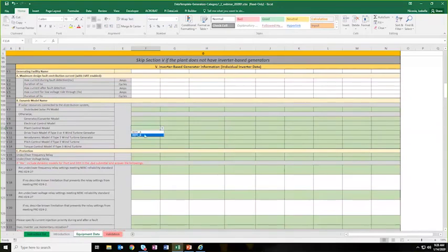Yeah, so here on the REPC model, I want to emphasize that REPC_B is preferred if you model multiple equivalent generators for the same plant and the voltage control is coordinated among those units. REPC_B has the capability to control multiple devices. It's better than the A because we have seen in simulation that when there are multiple generators in the same plant, they fight each other on the voltage control. It doesn't impact the overall system performance, but it affects how the generators behave inside the plant. But if you do use REPC_B, please be aware that all the parameters are based on the system MVA base. There is no option for you to use the machine MVA base. So you have to convert all the parameters, otherwise the simulation is wrong.